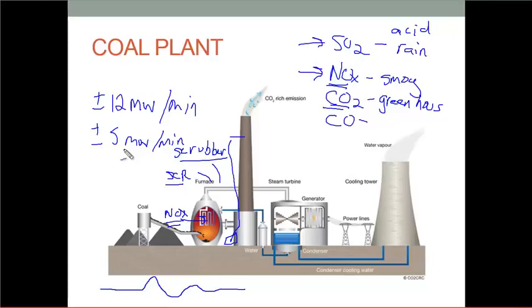So again, when your renewable generation goes up or down, the only thing you can do is to operate this power plant and swing the unit, and increase the amount of fuel. It takes a little while. You increase the fuel and you put more heat in here and you generate more steam. And then after a couple minutes, you start generating more electricity. There's a delay. And also after you take a little heat out of here, maybe you put a little less fuel in there, but it takes a little bit for that heat to dissipate and then for your generation to go back down. So you're kind of limited in what you can do going up and down.